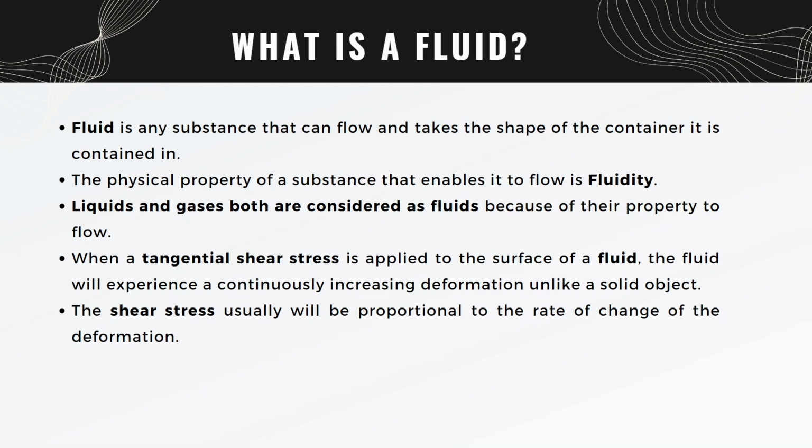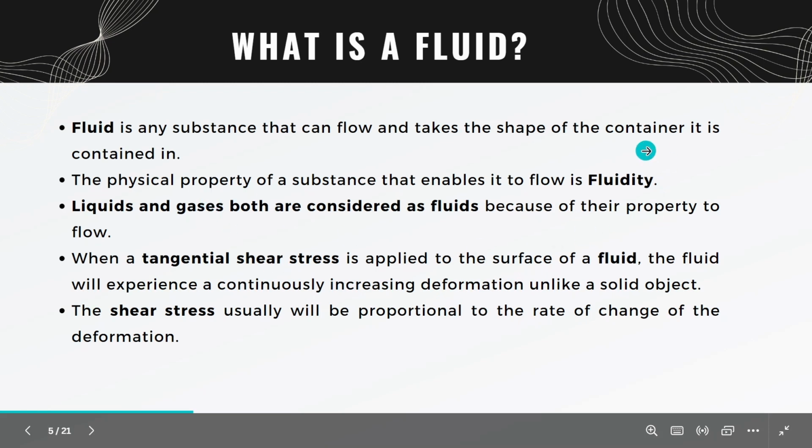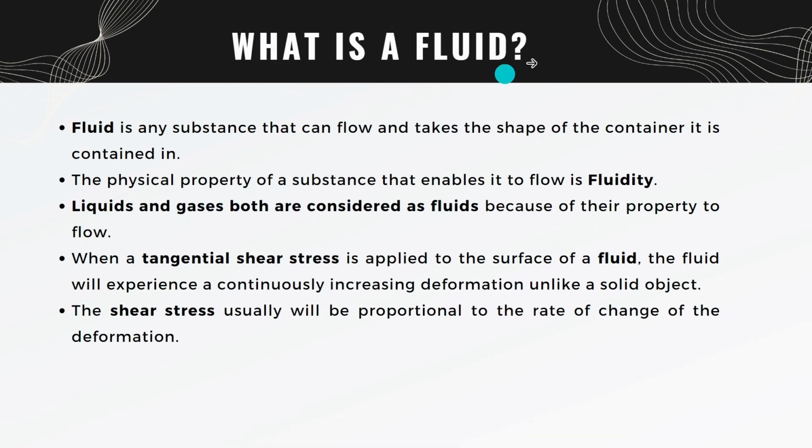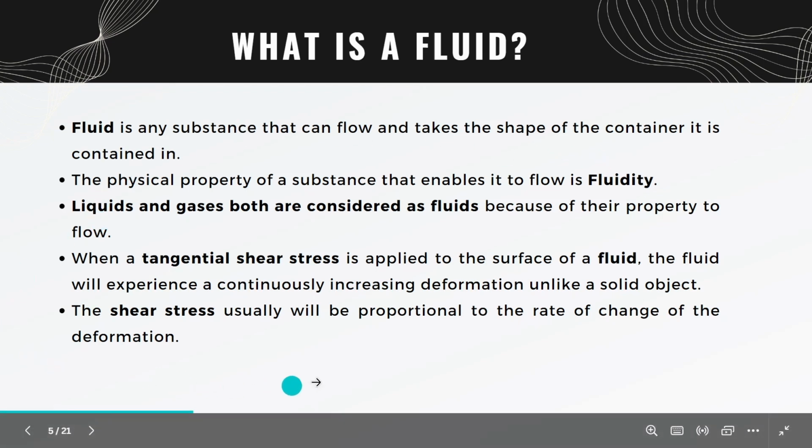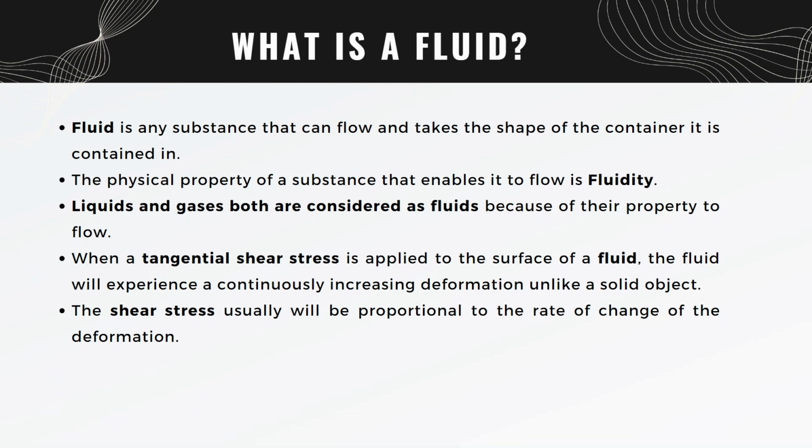Now, there's a branch of dynamics called fluid dynamics, which deals with the dynamics of fluids in general, and there's a special branch of it, aerodynamics, which deals with a particular type of fluid, which is the air, which we are discussing here. The more technical thing we are supposed to discuss here is this definition. It's rather a property of fluids, which says that when a tangential shear stress is applied on the surface of a fluid, the fluid will experience a continuously increasing deformation, unlike a solid object, right?